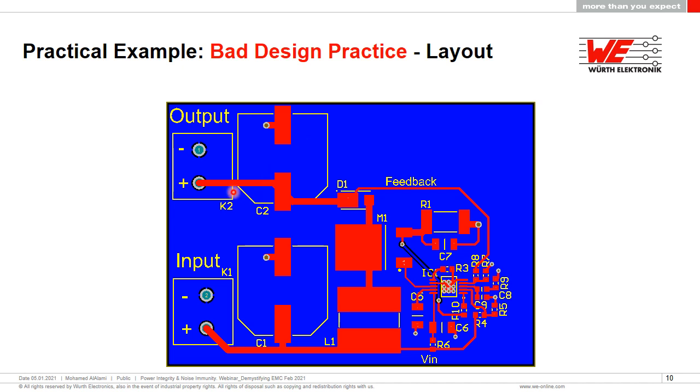So in here we see quite a wide range of issues that have not been designed in or considered, bad design practices. We've got a single ground plane. We haven't created a small enough loop, so the di/dt loop is relatively large, going through the resistor and the output capacitor here. So we are talking about making a big mess of it, but that was the intention. The intention was to make this as bad as we can make it, in a sense.